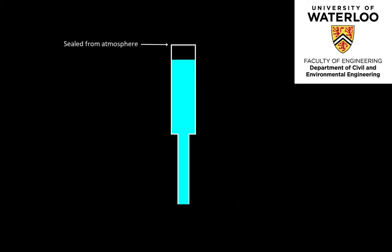The Guelph Permeameter is an adaptation of the Mariotte bottle whereby a modified reservoir has been configured. The reservoir is sealed at the top. The standpipe or air tube penetrates through the closed top of the reservoir, which is open to the atmosphere all along the length of the air tube. The air head space at the top of the reservoir then generates a vacuum if the water level begins to decrease in the reservoir tube.